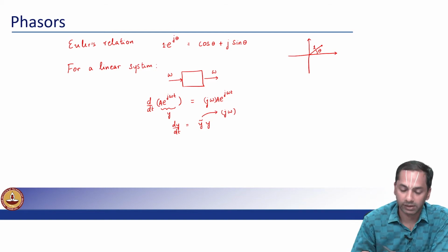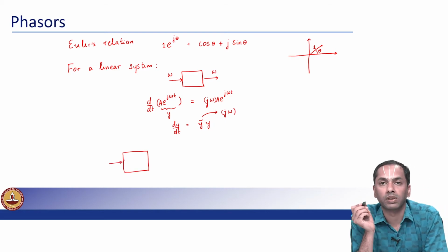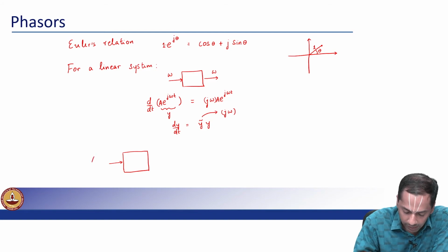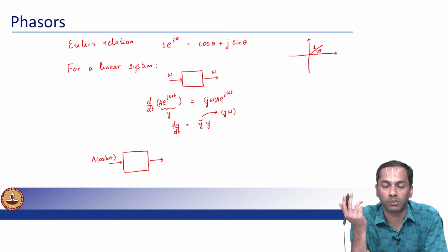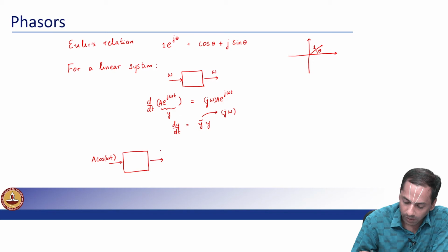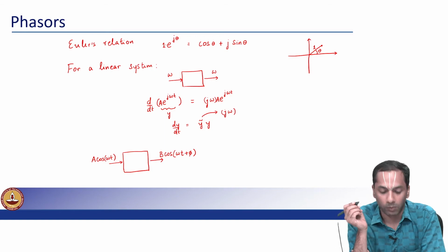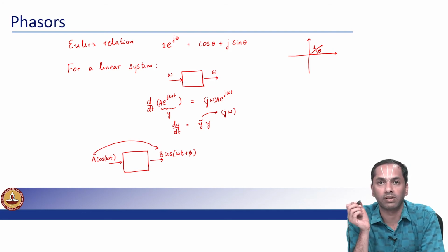With these mathematical relations in mind, we are going to say that no matter whatever the electrical circuit to which I am forcing a particular voltage or current at some frequency omega with an excitation that goes as a cos omega t, whatever output response, be it a voltage across a particular element or a current through a certain element, will always have a functional form where you can notice that the constant in front of the cosine has changed. We allow for changes in the scale.